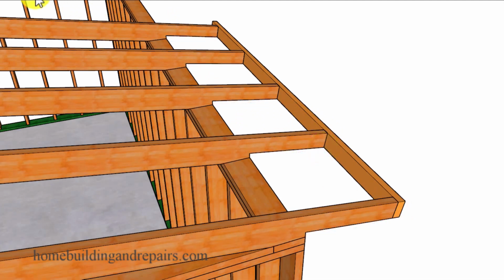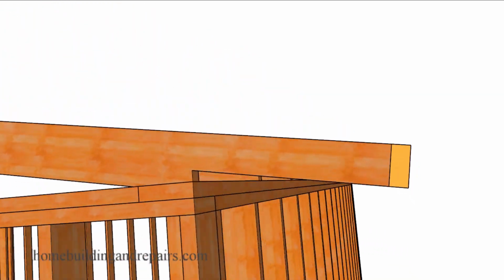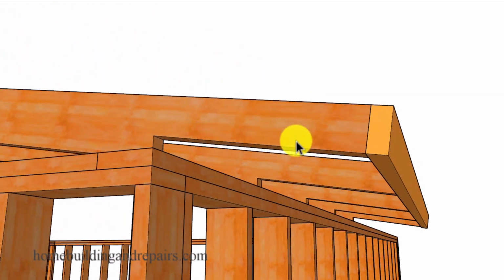And of course, we can rip the tails. This is another common method. I've used this one a lot. Even if you have 2x6 roof rafters, you rip the tails down to 3.5 inches or even 4.5 inches. Or, I hate to say it, even 5 inches if your fascia board is going to be wider than 5 inches. 5.25, 5.5 inches. Then everything should be fine if this is a 1/4 inch, a 1/2 inch, or even an inch smaller than the fascia board.